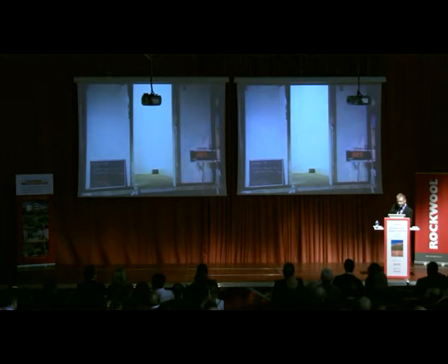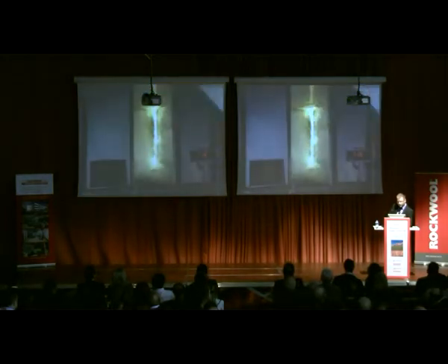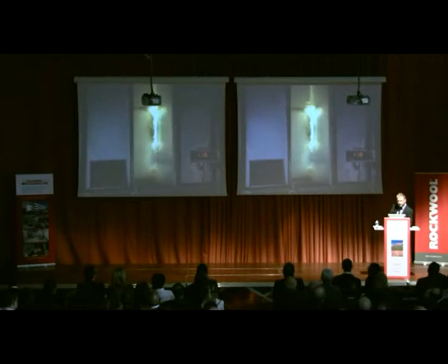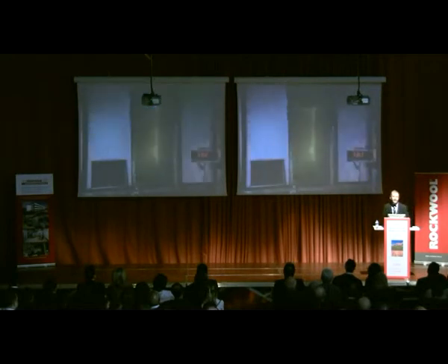And let's look what happens to polyisocyanurate or PIR core sandwich panel. The first panel, stone wool core, is mostly classified as A2 class. This panel is classified usually as B class. So you might expect, just looking at the figures, at the classifications, that there would be no big difference between them. But is this really the case?